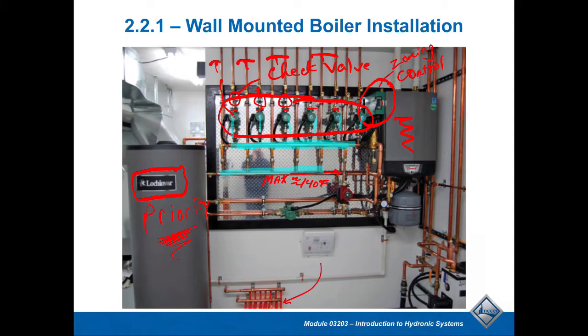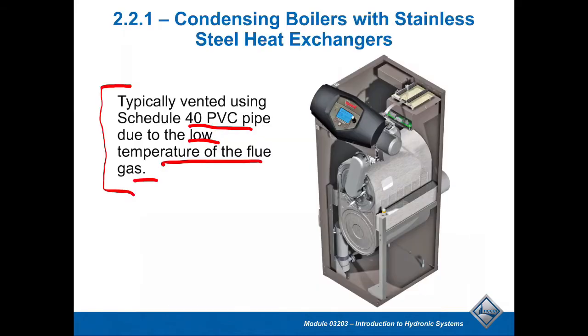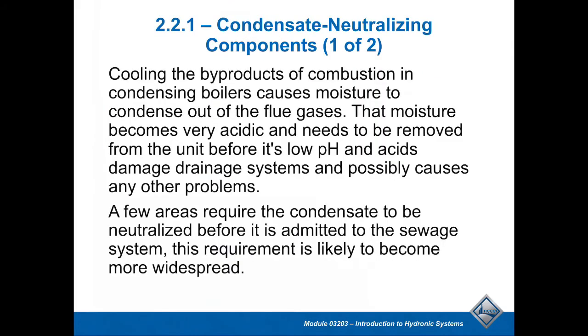The reason for that is that if I have that going in any higher than really in the 135 to 140 range, I'm going to run into a problem where the PVC pipe on the discharge, exiting your job here, is going to be warmer than that temp. So that's why we want to be a little bit careful on that inlet water temp. Be very careful of that. You can lead to some heat exchanger problems, depending on the boiler.